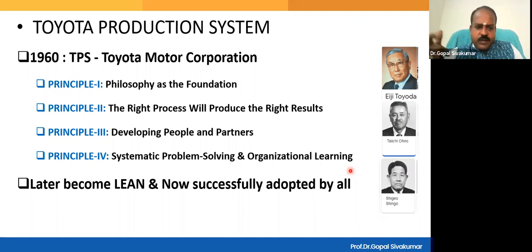Small changes, small daily activity. Making small improvements in the daily activity, like monitoring the tool angle, tool setting, machine setting, and doing some inspection, once in 1 hour, once in 2 hours. These are control plans. Whether I should take 2 samples or 10 samples. When I change my approach from taking 2 samples to 10 samples, that can make a big difference, isn't it? So these are called a control plan. At the same time, in the process, you should also remain efficient, because doing too much inspection sometimes may look meaningless. So we have to be effective, and at the same time, we have to be efficient.